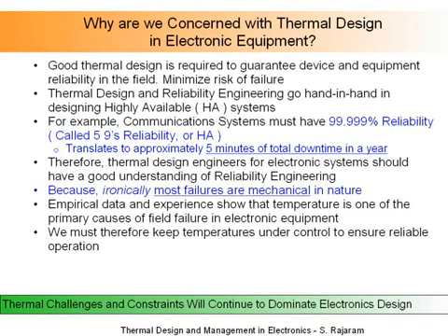In most communications equipment, there is a requirement for defining what is called a high availability system, HA. So what does this mean? A high availability system usually is referred to as 5 nines reliability, and what that means is that it is 99.999% reliable. In the real world, that translates to the fact that any equipment that is designed cannot have a failure of more than 5 minutes for a whole year.